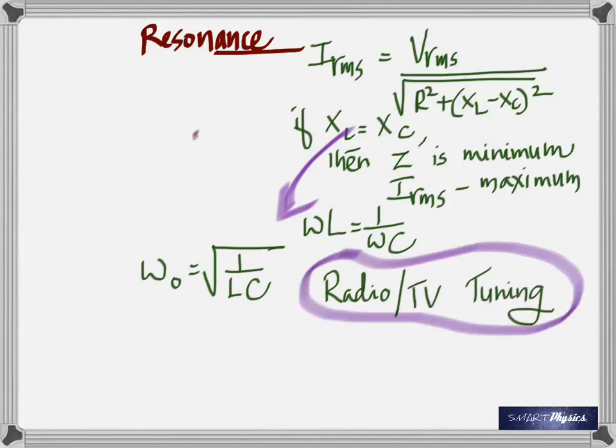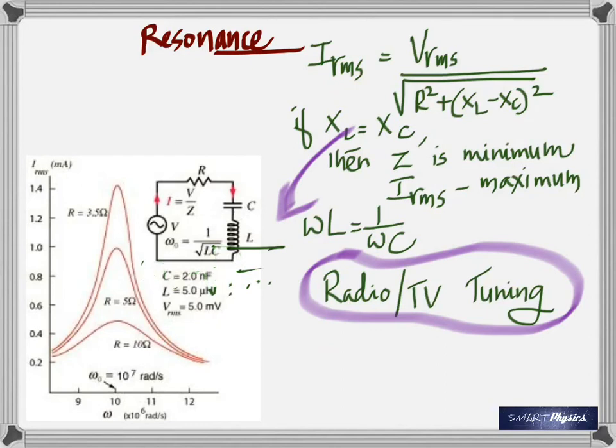Well, that's what we use for radio television tuning, which we discussed before, right? If you change the capacitance, you can change that. And I wanted you to look at this circuit. Before that, I want to ask you something. You've been so patient and listening. Come on. Does the resonant frequency depend on the value of the resistance? Again, does the resonant frequency depend on the value of the resistance? No, because resonant frequency is just dependent on capacitance and inductance, isn't it?